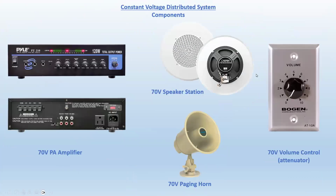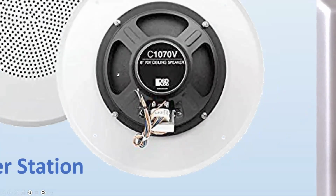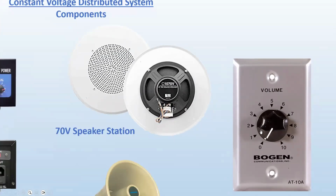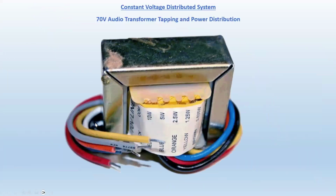Here. This is what the typical speaker station looks like. Here's the speaker baffle. Some of them are round, some of them are square, depending on the situation. And here's the step-down transformer right there. Here's a volume control. The volume control is not just a slider. It is actually a transformer, but instead of tapping into the wires, there's a switch that taps into it. I'll show you how that works later on, because we're running out of time here.